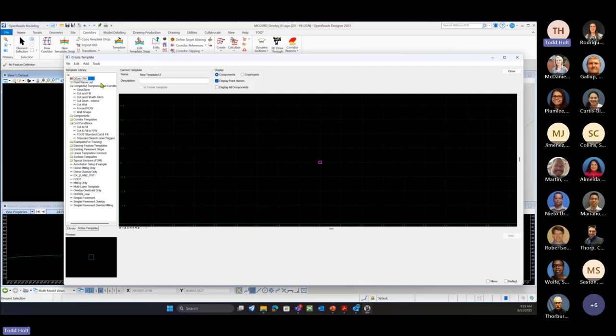This will just be a simple fill. We're going to do a demo for a simple fill slope. We're going to start pretty simple, but we're going to dissect what that end condition is and the different priorities of it. We're going to take a look at the component properties and the point properties and really get in there and dissect some of that.